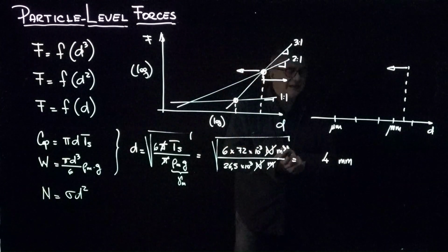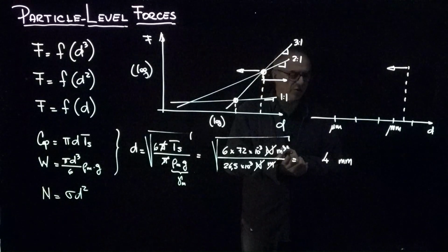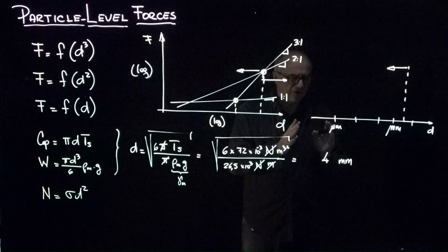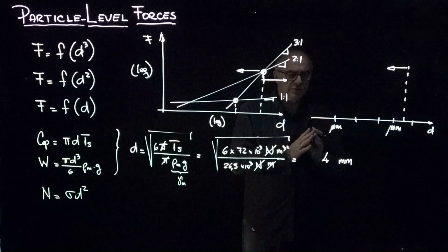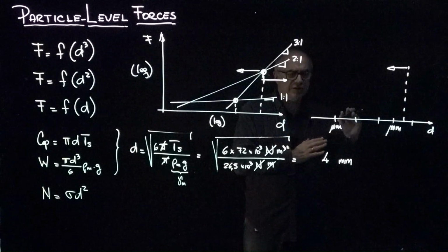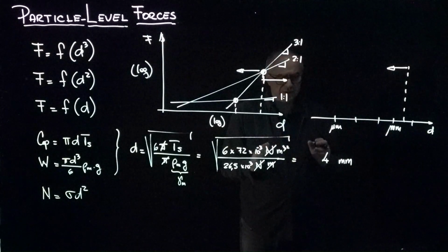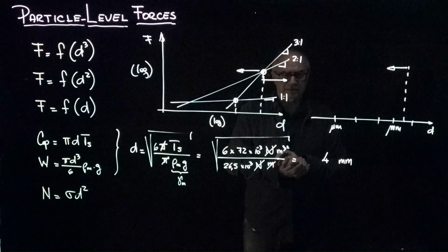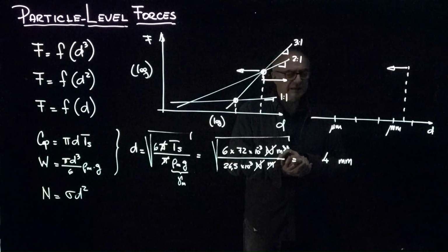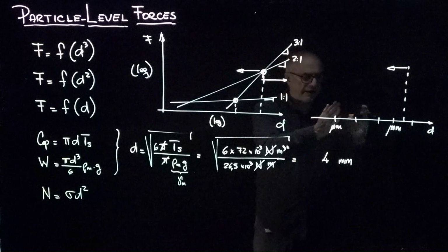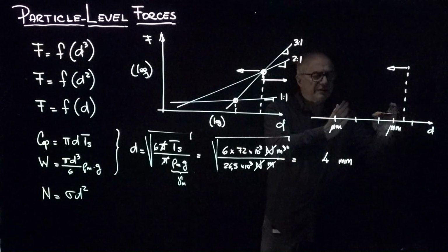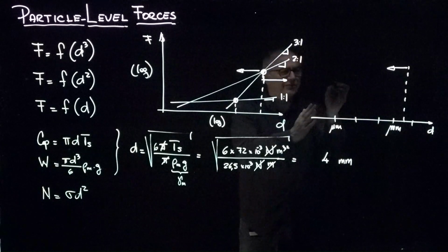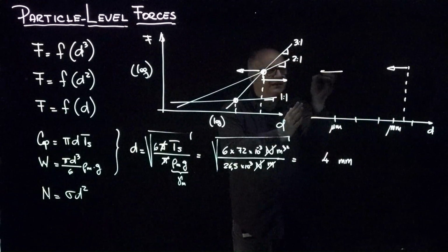But when you do the analysis, let me anticipate the following. I could compute the change in electrical forces due to changing water from fresh water to seawater for a soil buried 10 meters underground. And you will see that there is no effect, there are no volumetric changes for coarse particles, and that electrical forces gain relevance in the fine-particle regime.